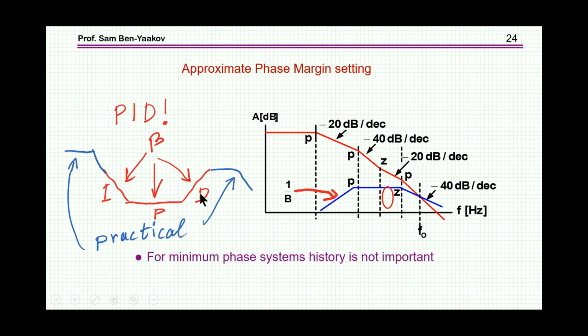And you can see that this is very versatile, because here I'm using this part, but if I wanted to say have the cross point here, I can use this part here, okay? So in this case, all that I need is the PI controller. I don't need this part here, so I can bring this one here, cross it here. I have a controller which is here. So by this method that I'm showing, it's really very easy to come up with controllers to close the loop at a given crossover frequency and with a phase margin that we can decide on.